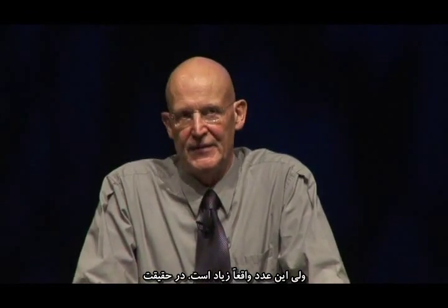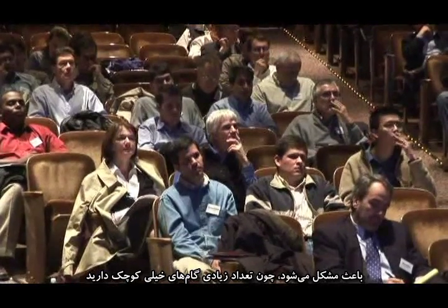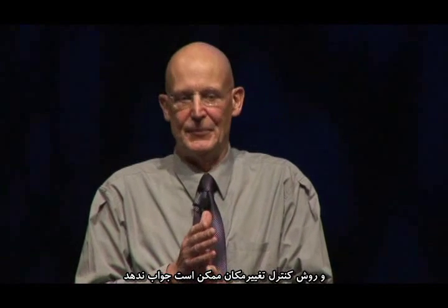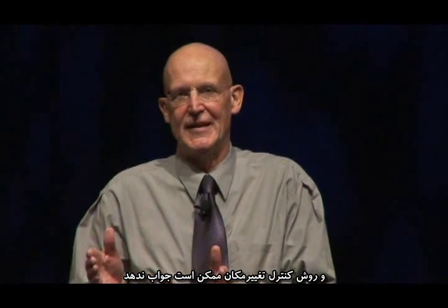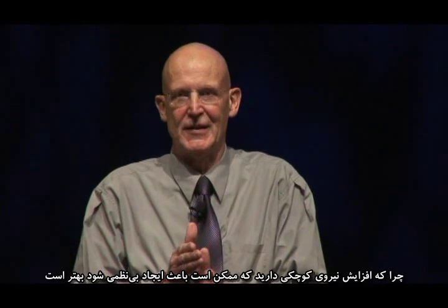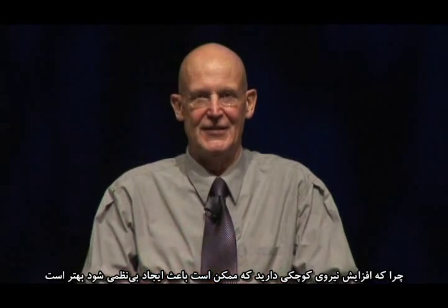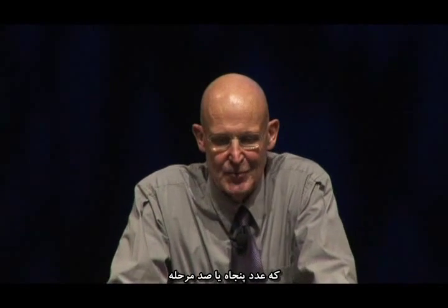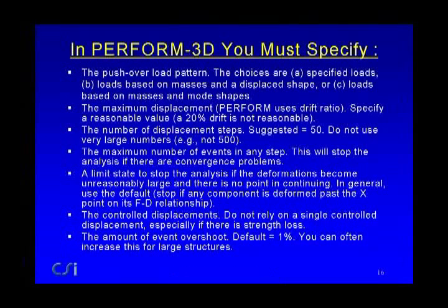And in fact, it creates problems because if you have a very large number of very small steps, the displacement control method can get a little unhappy because you get so little load increment it can get messed up. It's better actually to specify 50 or maybe 100 steps, but no more. You don't need to do any more than that.